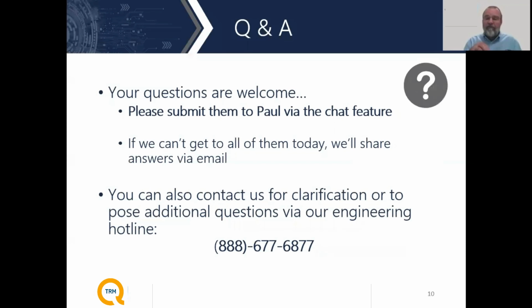with a flexible, small cover going on top of it, as opposed to having a robust housing. Because if you're going to be on a PCB inside of a unit, typically it's a box inside of a box scenario, and you don't need that sort of weather tight seal that you would expect on some of the other products. Conversely, if you're going into a part where you are going to be out in the weather and see other sorts of stricter environments, then you very often do want to have a housing around it, even if it is a bonded multi-layer PCB inside the unit. So that interface very often is defined by where it's going in the system and what the overall environment needs are.